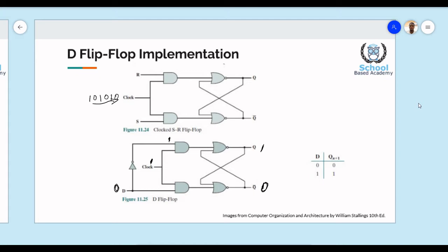And along with that 1 in the clock pulse, we're going to get a 1 value here. If we take the value of NOT Q, because our flip-flop is currently set, and we enter it into the NOR gate, we're going to get 1 NOR 0. This is going to give us a value of 0, which will force NOT Q to be 1. And the circuit has effectively been reset.